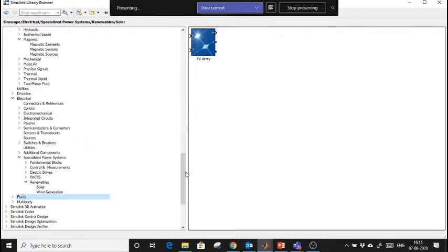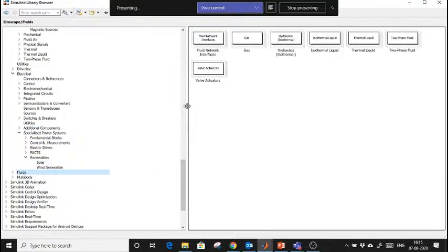Okay, I was telling what the difference is between a Simulink model and this physical modeling. See, physical modeling is bidirectional. Current can go left, right, up and down also. Currents are bidirectional because they are energy signals. If I am talking about a rotational body, then torque is bidirectional. So these are bidirectional.